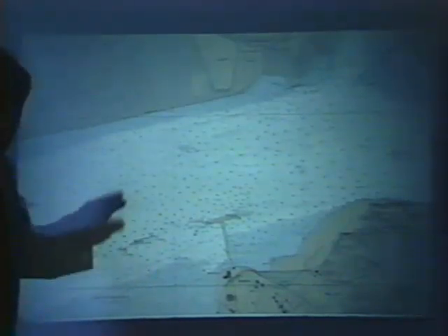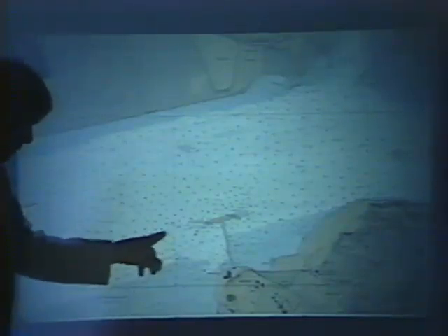Now, sometimes it's not possible to make it. That is, there's enough variation in the currents in both directions so that you can't avoid some shadow of the piles in the area. If you find that circumstance, then you want to cant the angle a little bit so that you have downwelling at the wharf face. But normally it's not too much of a problem. You can just line it up and minimize the effect.